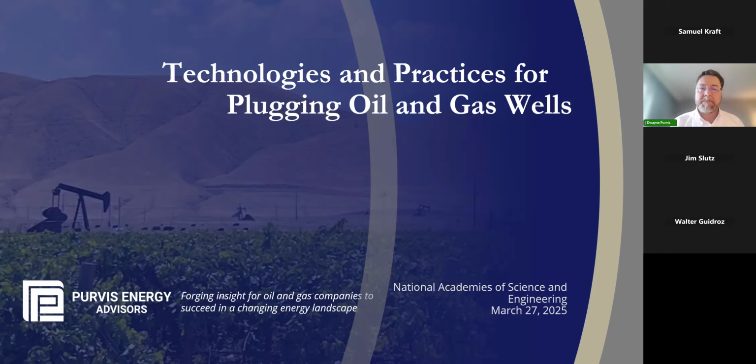Cement is indeed very hard. It's not very sticky. By all accounts, the best way to install it is rock to rock, where you have a rough, tortuous path for it to interface. But of course, cement is still brittle and steel is still corrosive or corrodable. We do see a higher failure rate in older wells than in newer, and there's no doubt about it that we've gotten better at well construction. And it's a great point, borne out by the most recent project by Petroleum Technology Alliance of Canada, that the company doing the work and the person doing the work, that is how you do the work, is a first order variable in how effective it is. It is at least as important as the technology that is used.